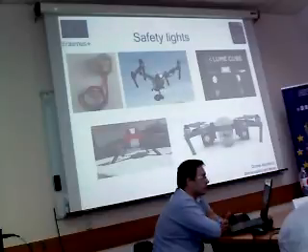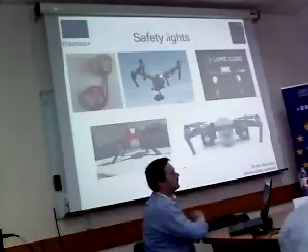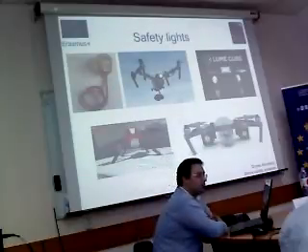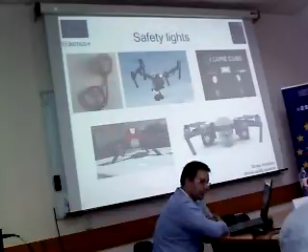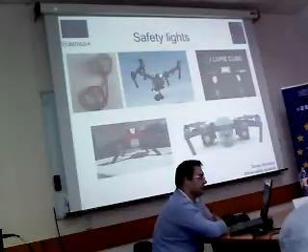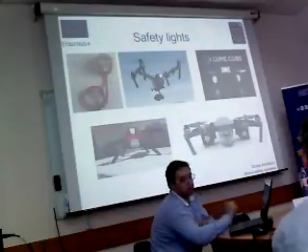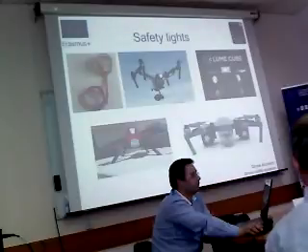So, as an example, according to FAA regulation, the Part 107 rules, you can fly your drone during the day. And daylight is from 30 minutes before official sunrise to 30 minutes after official sunset. If you are flying during that 30 minute twilight period, you need to have lights visible for at least 3 miles. That is the regulation from the FAA.